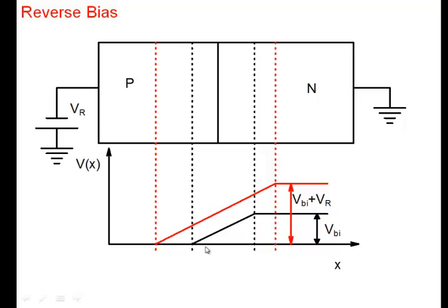If the doping is uniform, it will change in a quadratic manner. If the doping is non-uniform, it may change in a more complicated manner. These are schematic drawings. The only thing that you carry from this particular picture is the voltage drop initially is VBI and the voltage drop after that becomes VBI plus VR. Don't carry the fact that you see it linear.